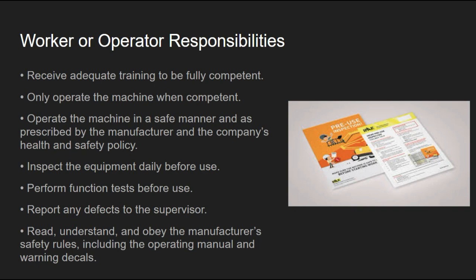Inspect the equipment daily before use. Perform function tests before each use. Report any defects to the supervisor. And read and understand and obey the manufacturer's safety rules, including the operation manual and warning decals. So listen, if something doesn't seem right and you shouldn't be using this machine, let your supervisor know. Let's get it corrected so there's no further issues.